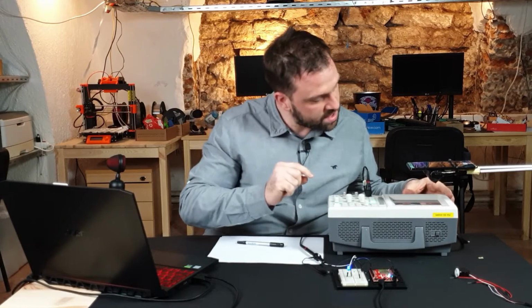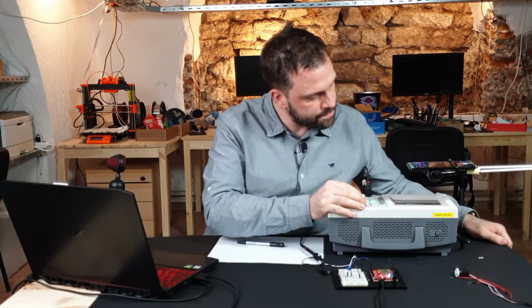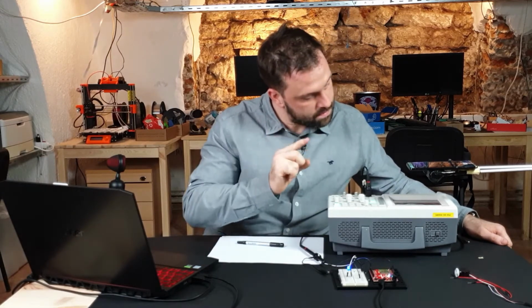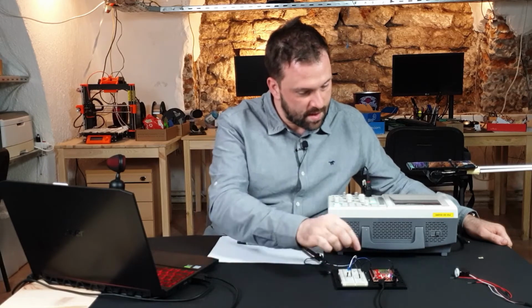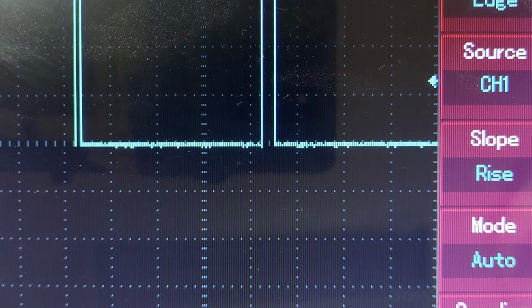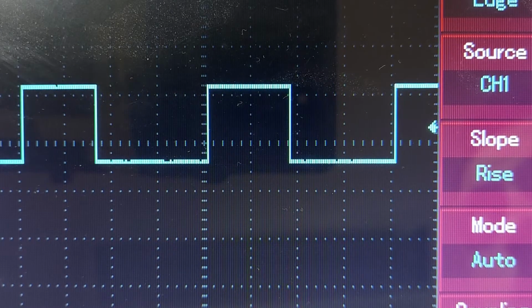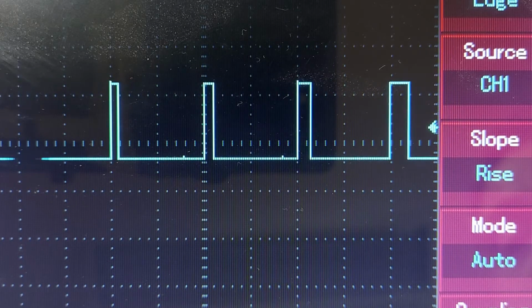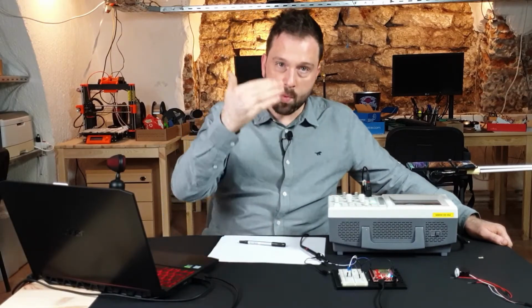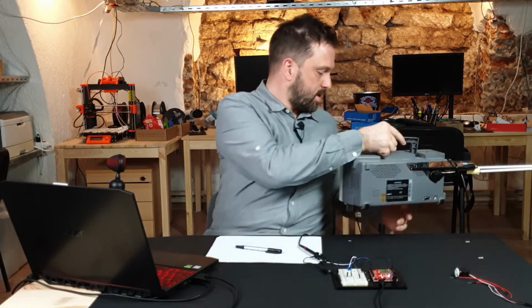And if you take a look here, let me just set my oscilloscope, give it some time. Yeah, it's a bit confused now. I'm gonna scale it down so you can see the signal, and voila. Let me just scale this as well. So it changes much slower. The change is slower because it's only 5 times per second. And you can actually see it also goes from 0 to 255, but it's blinking because the change is not fast enough. And this is how PWM works on LED. Remember, it just lowers the brightness. And this is how LED dimmers work in your home.